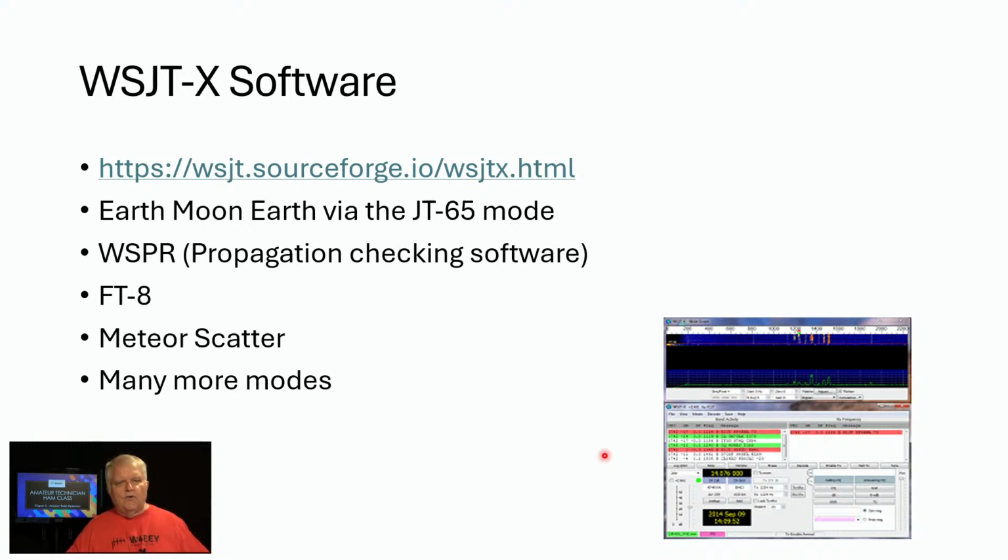It uses timed sequences, 15 seconds of transmission, 15 seconds of reception, and it can work with very, very weak signals. It trades time for signal strength. So even when bands are dead, when the 11-year sunspot cycle is working against us, with FT8 you can still make contacts.